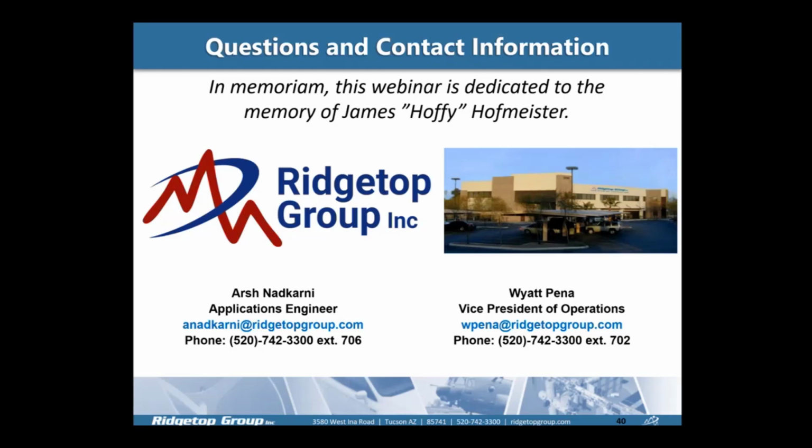What we typically let our customers know is the hard part about prognostics isn't necessarily processing feature data to determine the SOH and RUL. The typical hard part of developing a PHM solution is really understanding the failure modes and the data processing requirements and the sampling rates and mounting locations of a particular application.